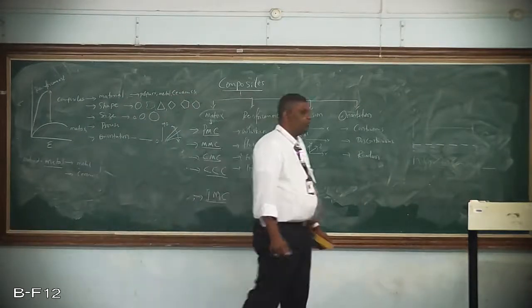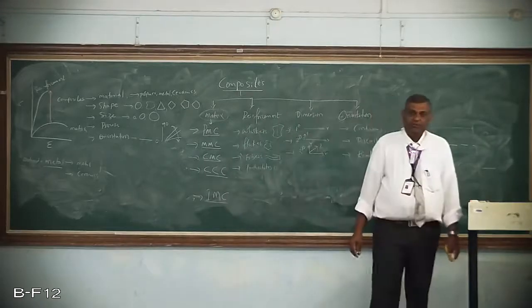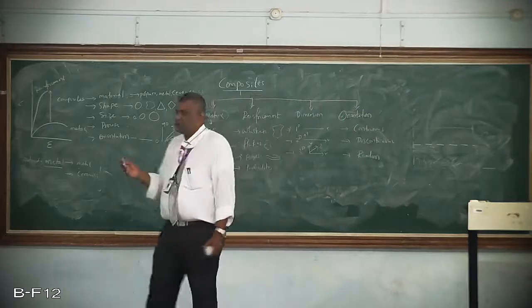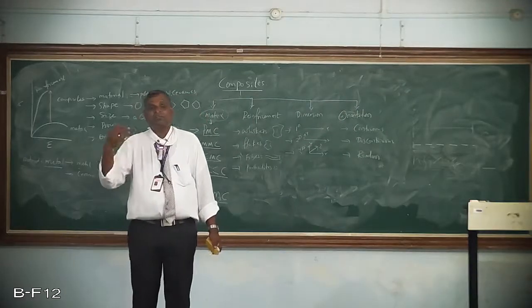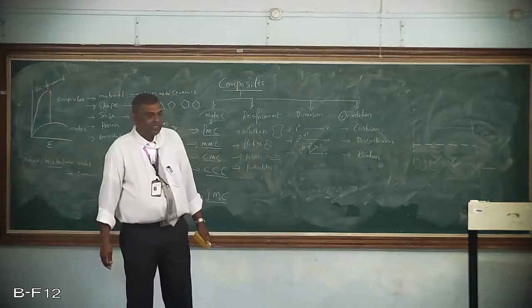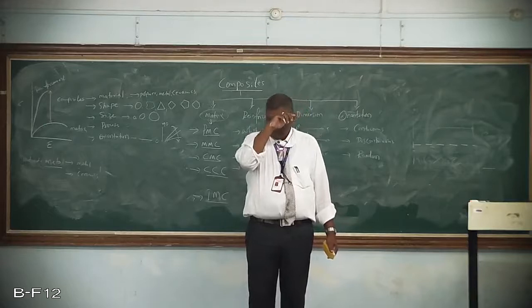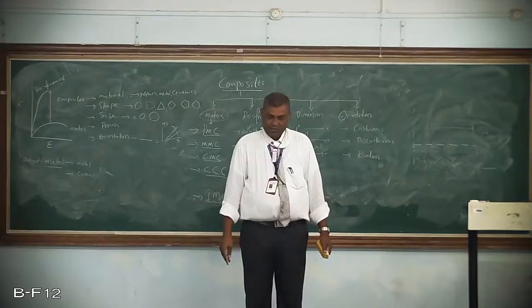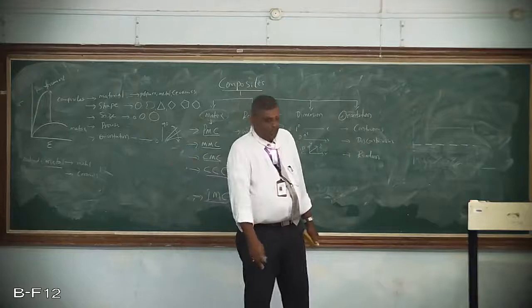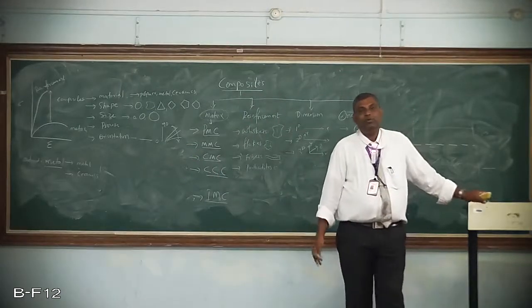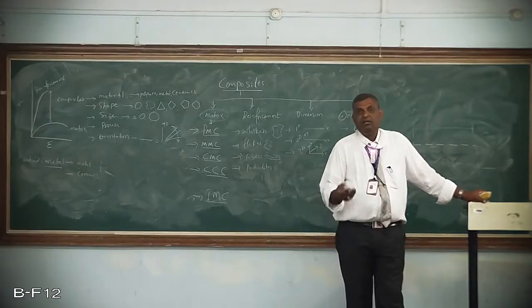Now if I want to improve the strength of the aluminum, by various alloying or other processes, I cannot increase the strength of aluminum to the maximum. I can increase it only considerably. By alloying, I can increase the properties by just some 15 to 30%. By the composite method, I can improve the properties up to 3 to 4 times. Basically, aluminum is very soft in nature, with low melting point, low strength and low density.